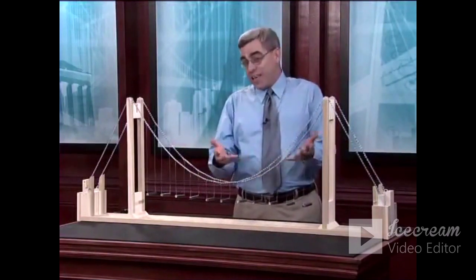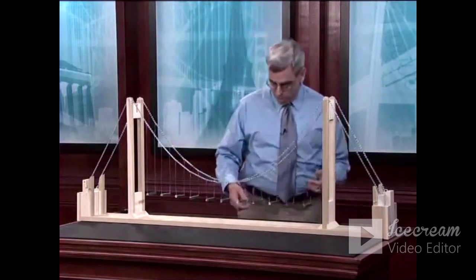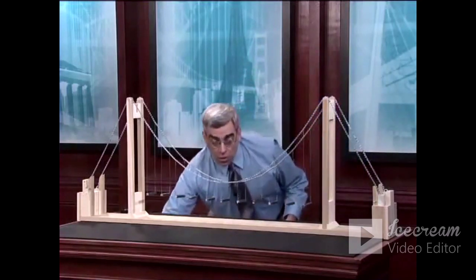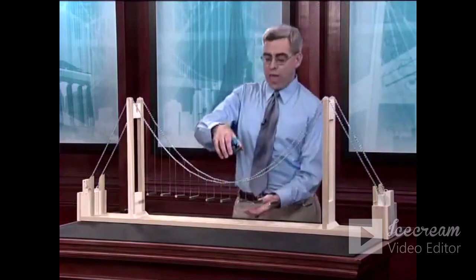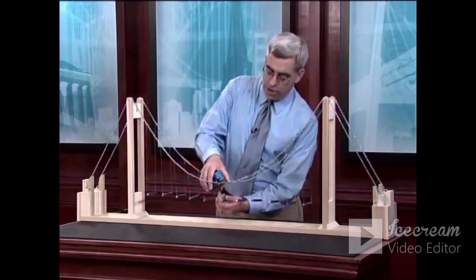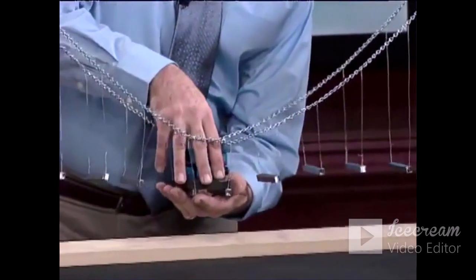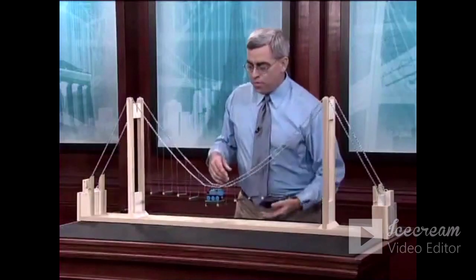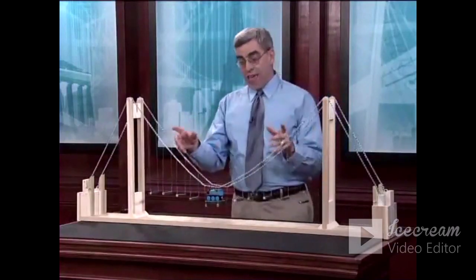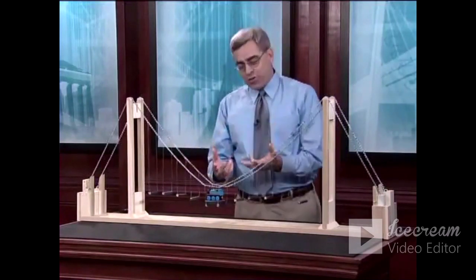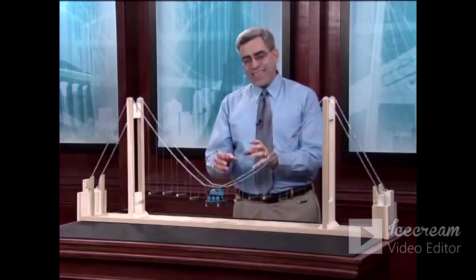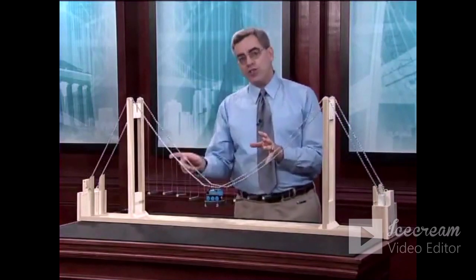What happens if the loading isn't uniform? What happens, for example, if a heavy vehicle like a train or a heavy truck is crossing the span? Well, when that heavy vehicle gets out here to mid-span, note what happens. Note that the parabolic shape of the cables has now become distorted into something very different. One of the characteristic features of a cable structure is that it changes its shape in response to changes in applied loading.